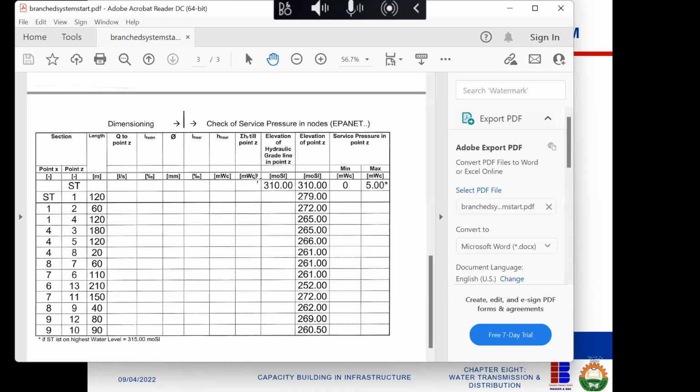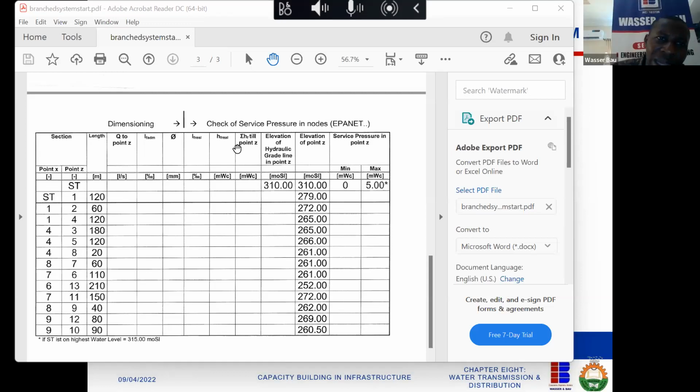Those of you that are civil engineers, when you do your design, there's this thing we call quantity required, quantity provided. Sometimes when you do your design it will give you Y16 at a spacing of 200. Well, you will say, no, I will use Y16 at a spacing of 150. There's a nominal design and there's optimized design. I think everybody does it.